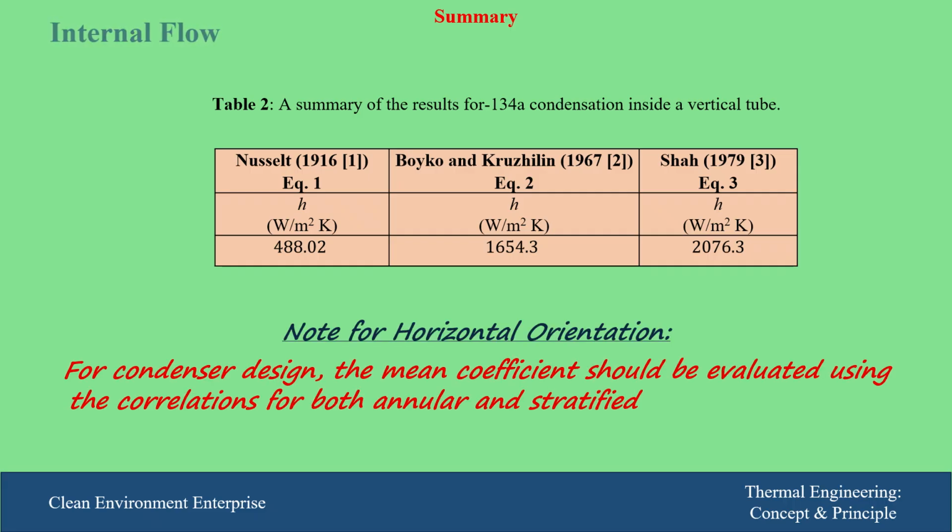We should know that for condenser design, it is used to evaluate the condensing heat transfer coefficient for annular and stratified flow, and we usually should select the higher value in the calculation of the overall heat transfer coefficient of that heat exchanger.